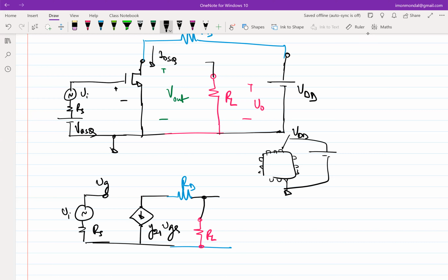Yeah, right. So essentially, what you're implying is, even though it looks like, since there is no voltage source in the incremental equivalent, we don't have sufficient information to tell whether the biasing picture will be appropriate. If we have to translate it to the biasing picture, we'll again have the same problem, because even though in the incremental picture RL looks to be connected between a ground and some terminal, in the biasing picture I'll have to insert VDD within this loop somewhere.